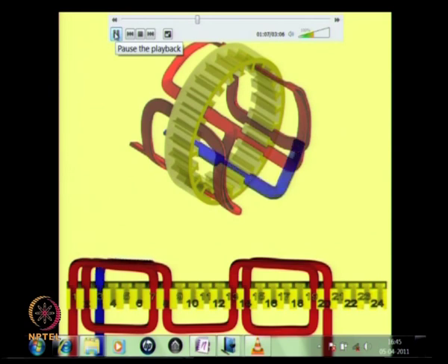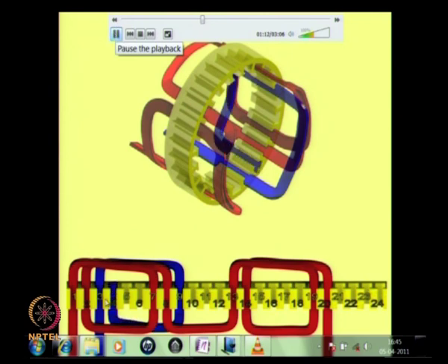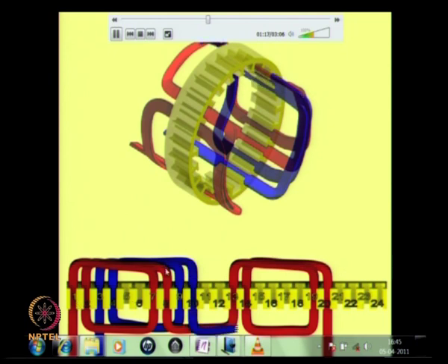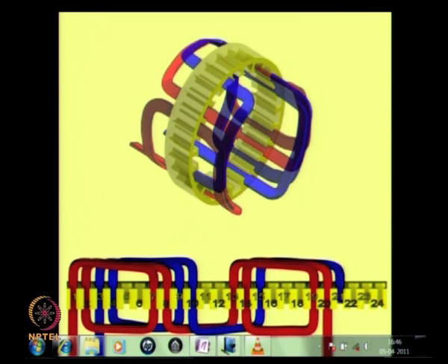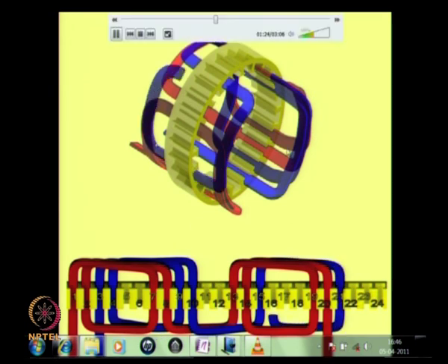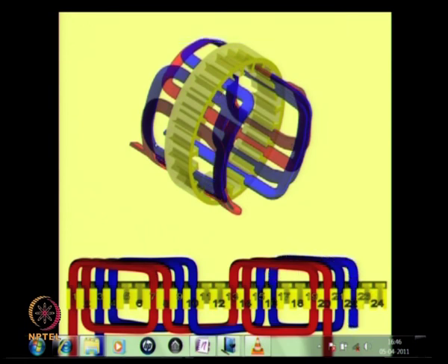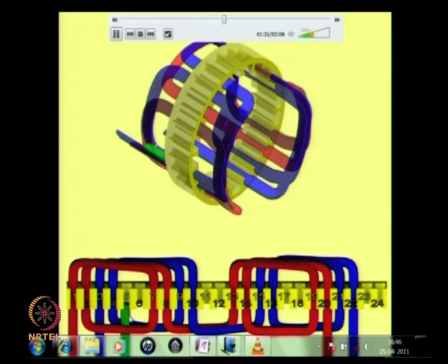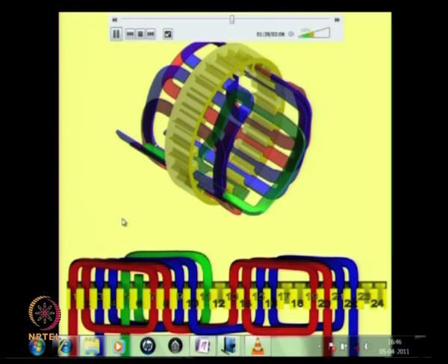This is the winding in the next phase. So, the B phase. Now, that is occupying 2 more slots in one pole area, and this is wound. So, you can see how this happens here. The actual situation looks like this, whereas the developed view, this is how it happens. And then the third phase, we have shown this by green, one can call it RBY perhaps, because yellow would interfere with yellow, this has been made as green.